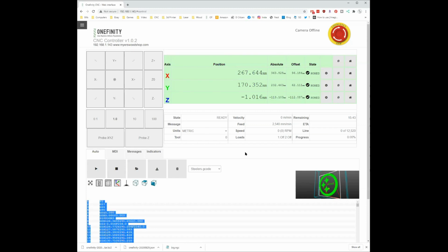Well, you could potentially do it relatively easily, because on the right side, it's showing you the line number of G-code that it's on. Absolutely. So if you hit stop and you know you're on line 870, you can delete from 870 up, create a new file, and it would start. Theoretically, yes. I should try that one day and see if it actually works. But end mills are expensive.